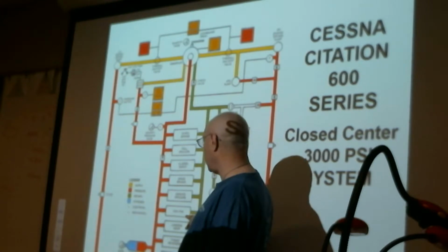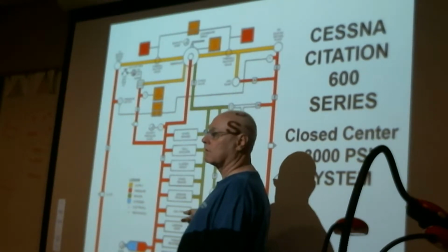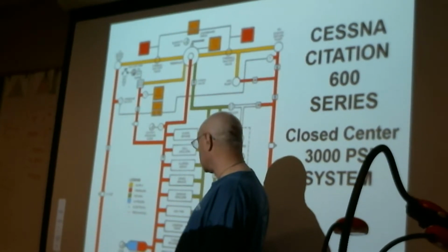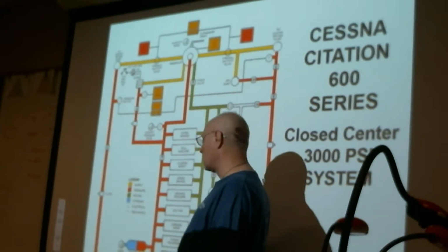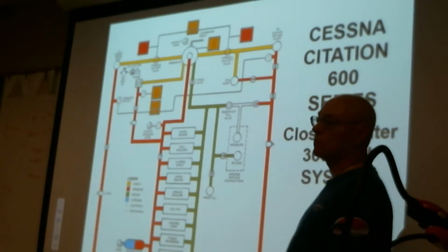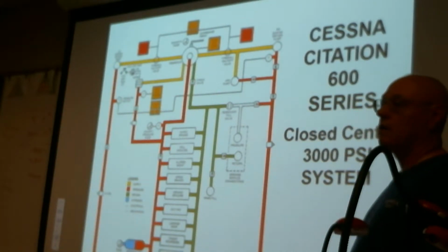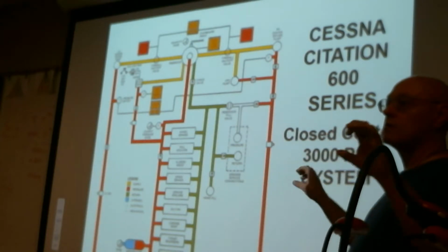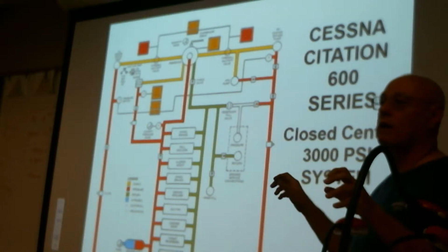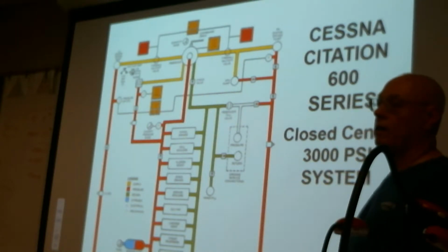Environmental control unit fan. So they have a fan for cooling. The landing gear retraction and extension system, thrust reversers, and nose wheel steering. It would be impossible to do something like this with an open center hydraulic system. You would have a series of valves that would all be in series with each other, and you could only operate one thing at a time. So again, we're not going to do that.